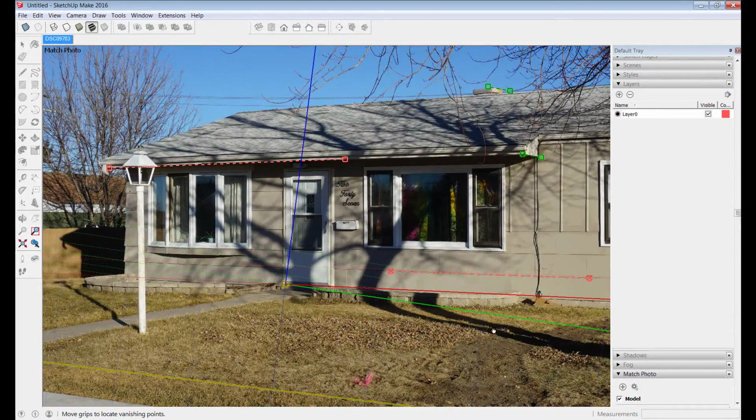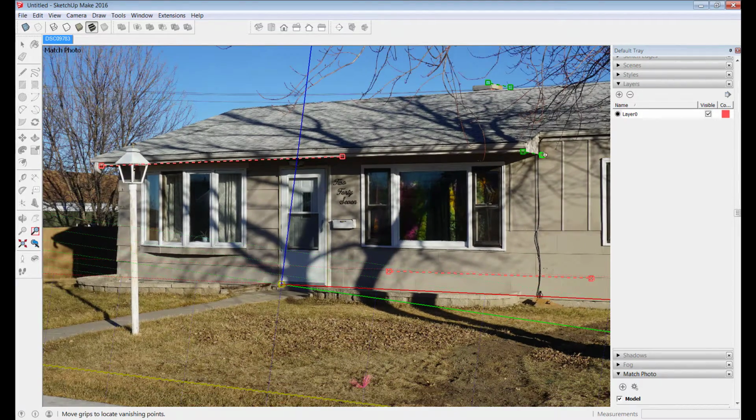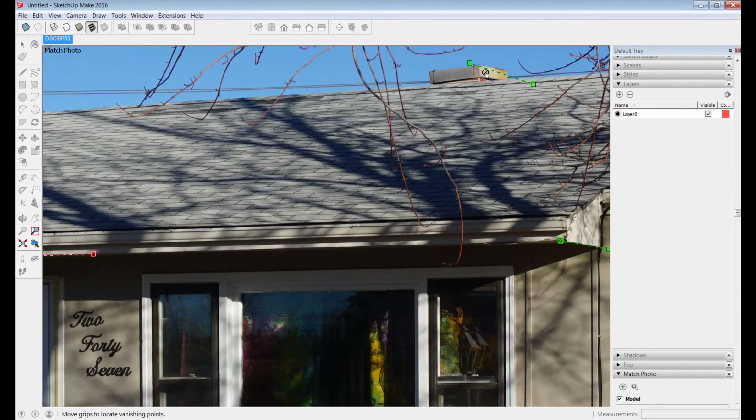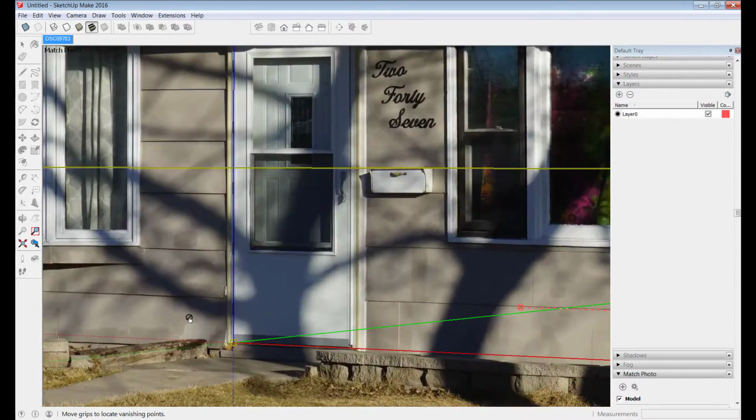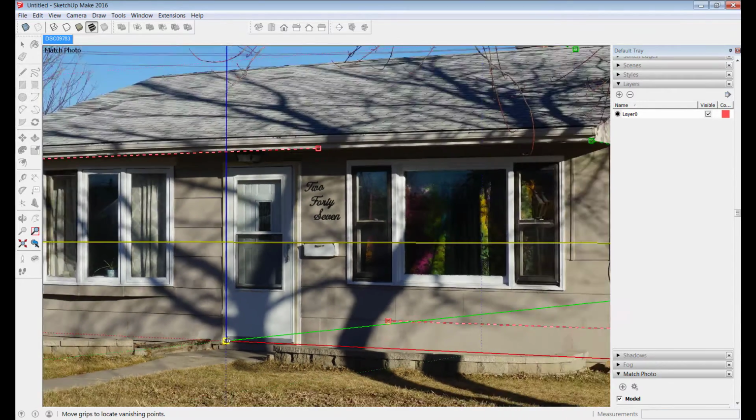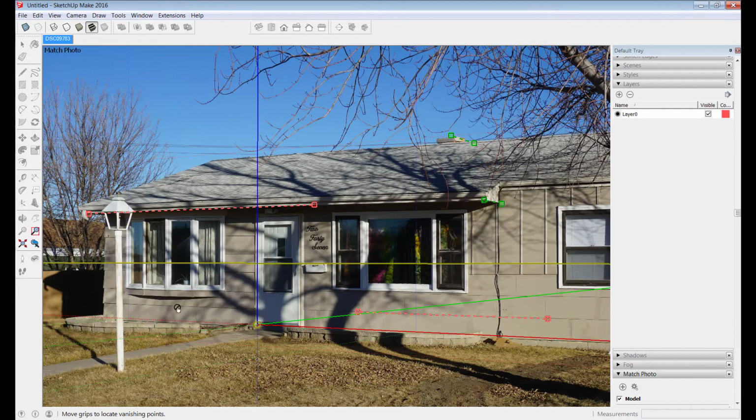And the way I fix that is these red lines, I'm real confident of those following a level surface that goes right to left, but I'm less confident in the green direction because I have such a short reference point. So I'm just going to take one of these and cheat. You can see up on that chimney cap that's barely moving, and it has a huge effect on the vertical axis. So I'm just going to assume that that chimney cap isn't that good of a reference. If I zoom in, you can see it looks like it's 1.5 inches off in the horizontal, but that's straightened out this blue axis so it's running nice and parallel to the door. I hope that thought process makes sense.